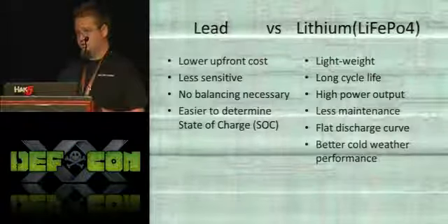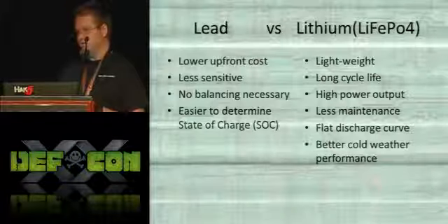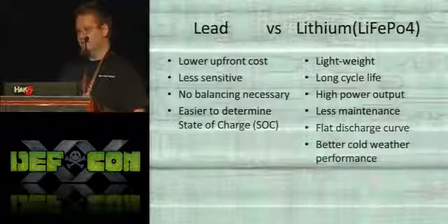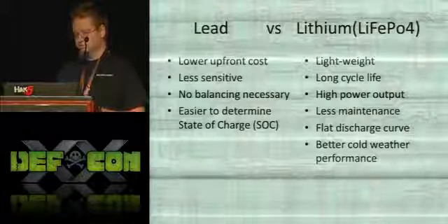There's no balancing necessary with lead because it self-balances at the top, whereas with lithium, you have to make sure all your batteries are at the exact same capacity. Otherwise, one of them will go over before others get fully charged.